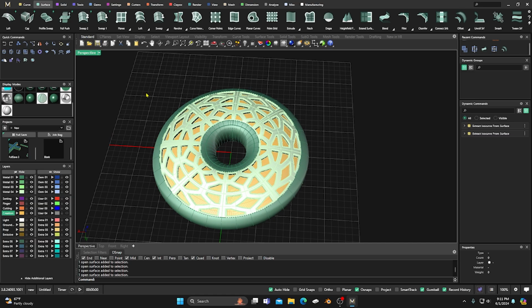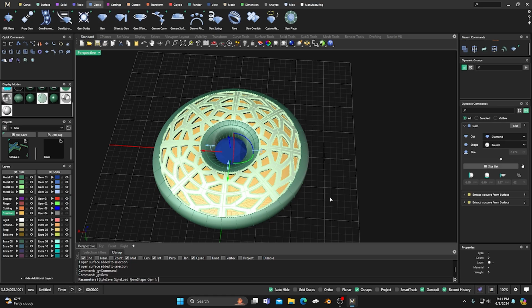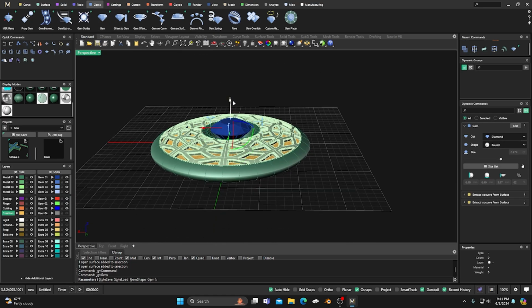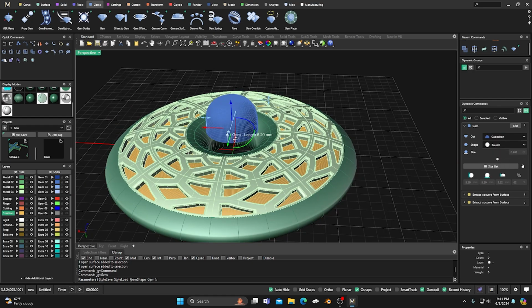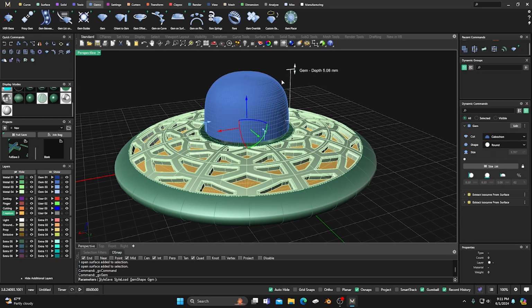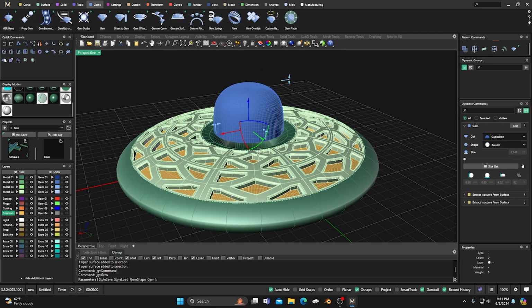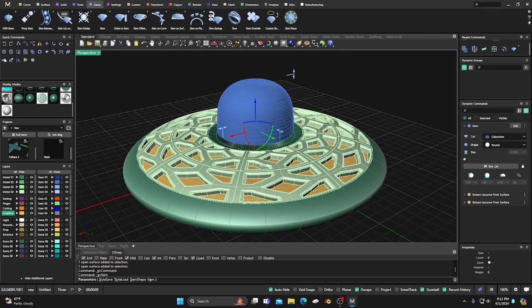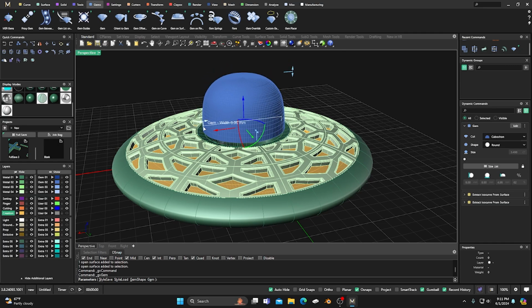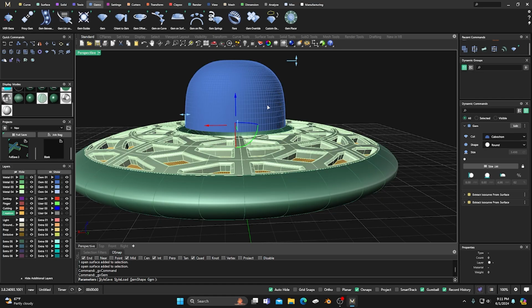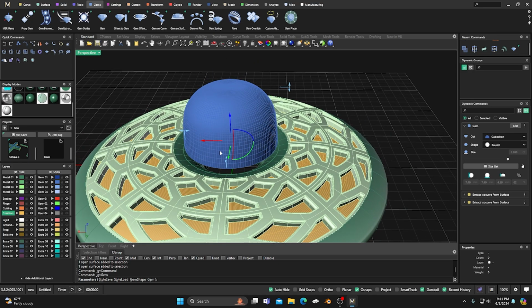Now what we want to do is go ahead and maybe we want a center stone right there in the middle, right? So we'll go to gems, we'll go to select a gem, and we'll pop that puppy up a little bit. And we don't want a diamond, maybe we want a cabochon, right? Now there's something with the cabochons is that if you select this, it kind of 3Ds everything. It's not something that you can really manipulate fairly well, right?